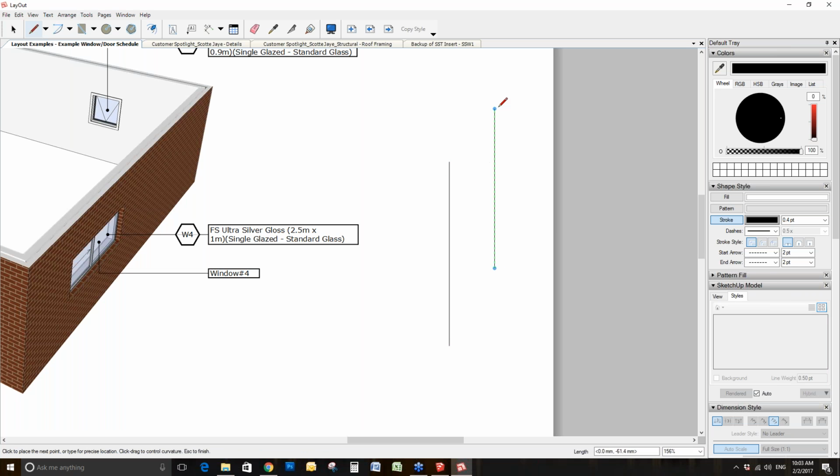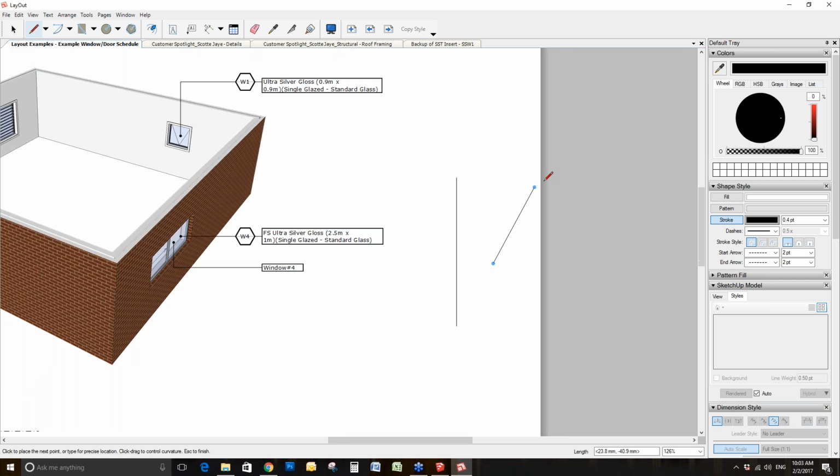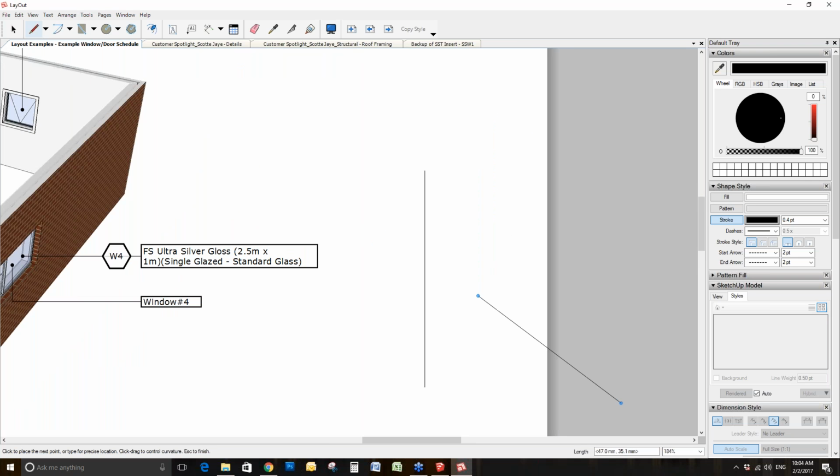So for example, or that line I should say. Now, for you, 61.9 millimeters is what it actually is on the page in reality. But if you're wanting to draw, for example, a 1:100 scale or a 1:50 scale, you just need to do the quick calculation in your head. So if you want to draw a meter long wall and it's at 1:100, then you know what you need to type in.